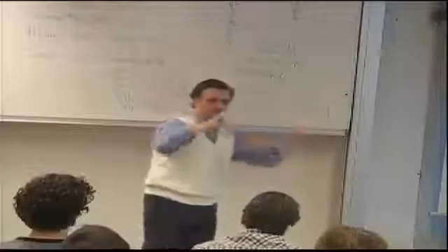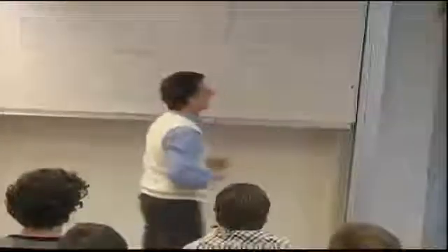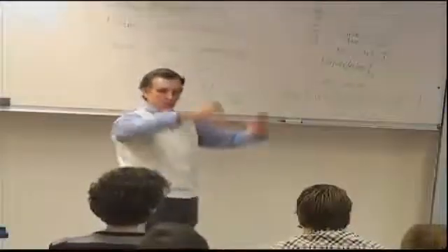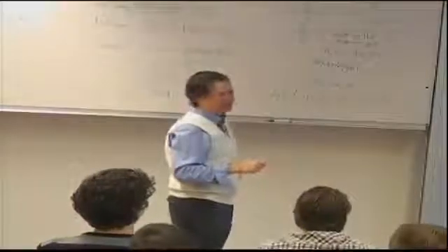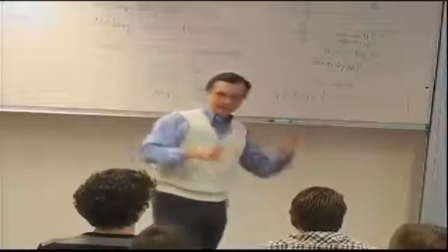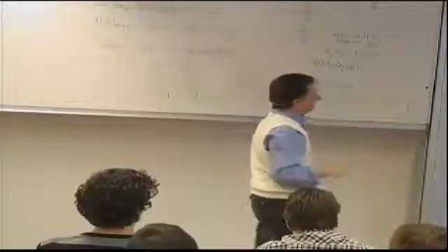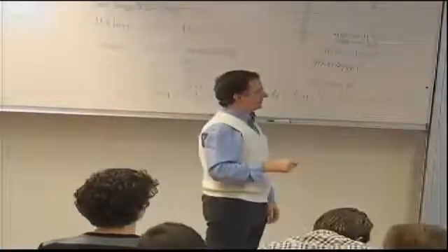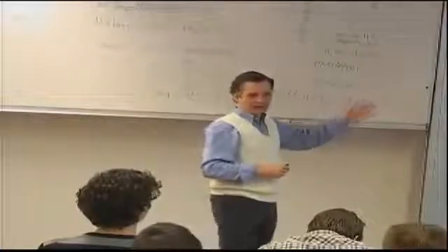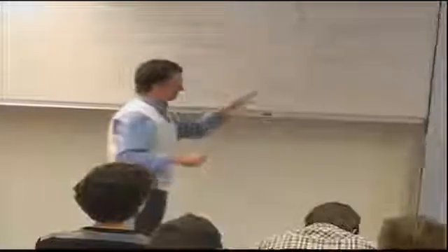So for those of you who thought that after the second year torsion and Prandtl stress functions you were done, I'm avenging myself on you here. And the twisting moment, mxy, or the torque T, is 44.48 Newton millimeters per millimeter. Remember, these mxy are, in classical laminate plate theory, per unit width. So these are per millimeter width. The value is obscure, but if you translate this to English units, it will be a very nice round number, but still I'm using English units because of my background. So that's the applied load.